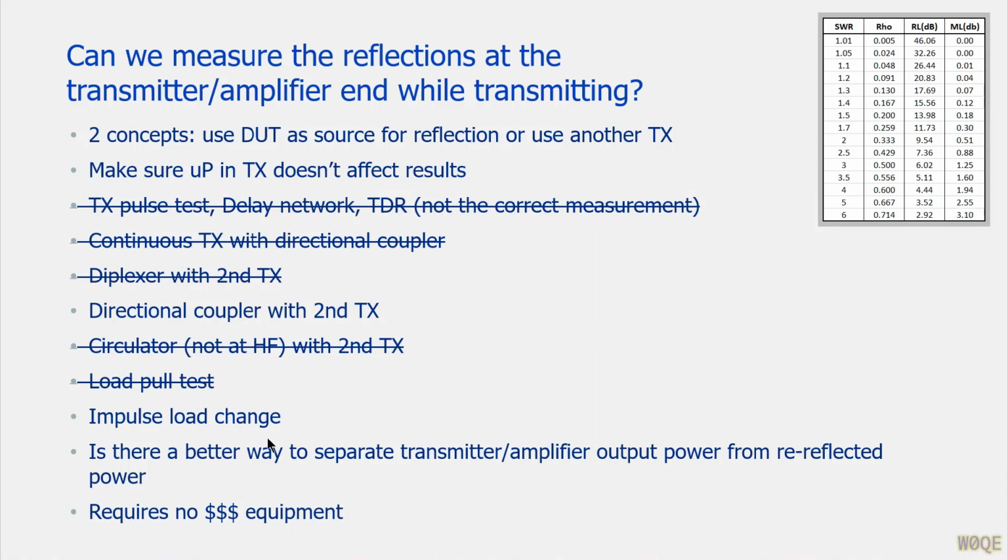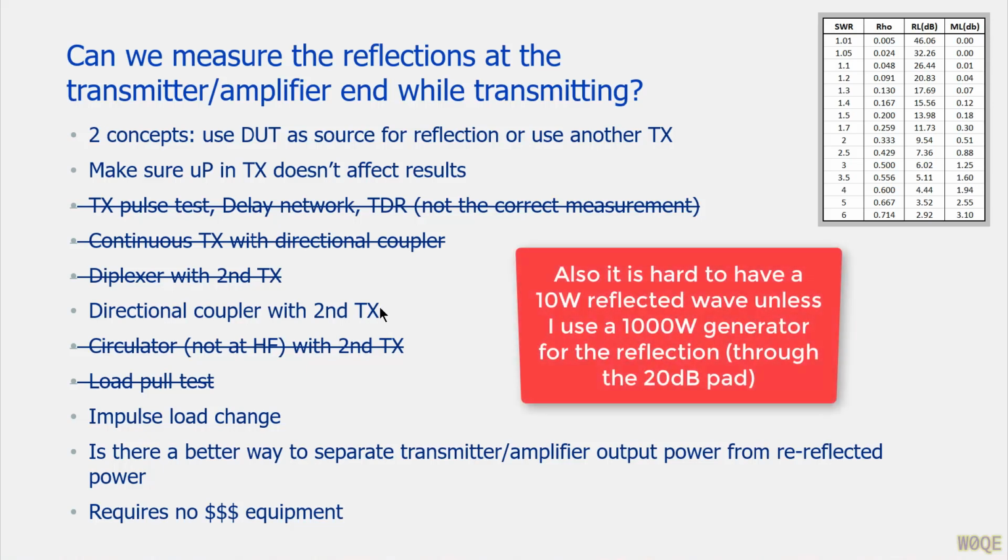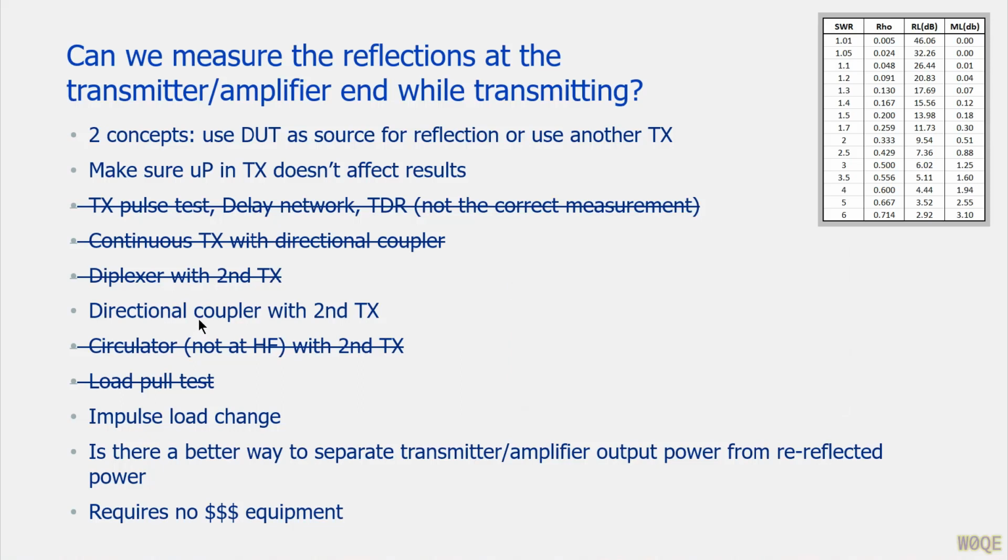And I'm not so sure that both of these don't have a fault to them. The fault with doing it this way is that the second frequency I'm putting into the transmitter really isn't the same as the output frequency. And because of that, you might argue that that's not correct. It has an interesting characteristic, though: I see all the phases. Because if the two frequencies are different, as the one frequency and the other frequency go through time, I see every phase of the reflected signal relative to the transmitted signal occurring. When I did this with a 20 kilohertz spacing, they occur in 25 microseconds.